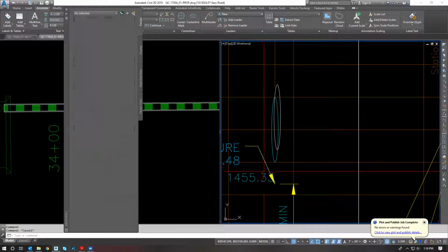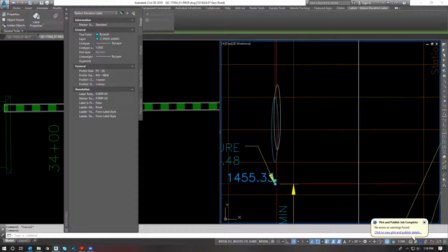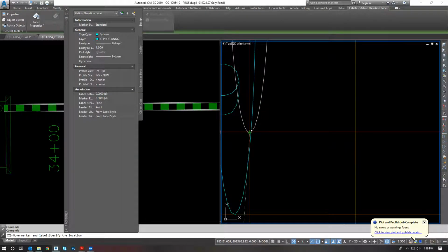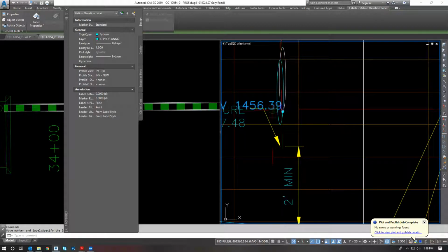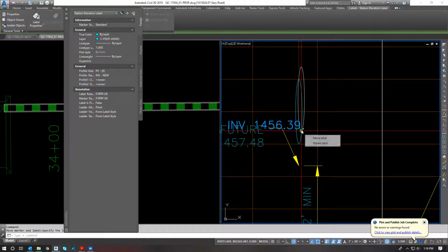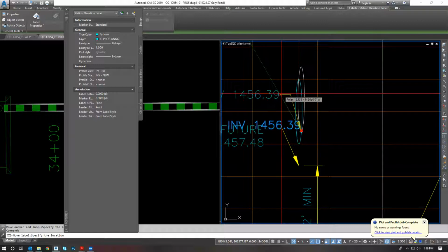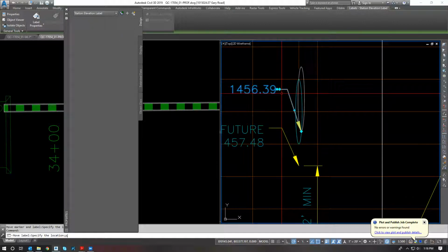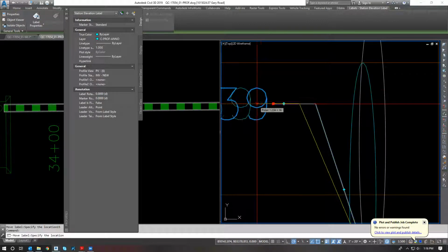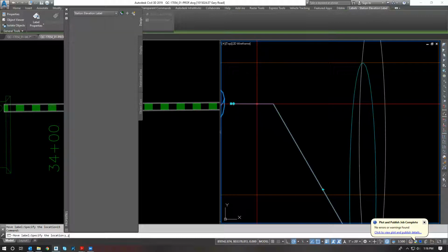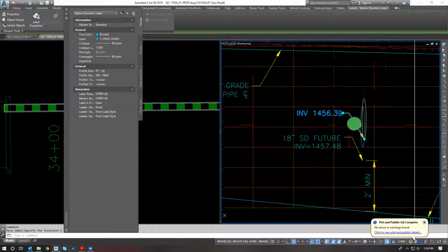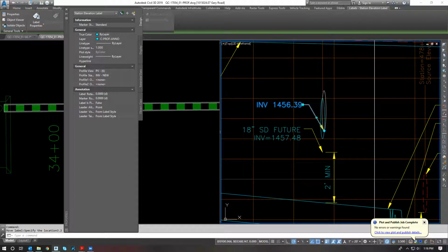So we can drag our dynamic label over to the pipe network part here, and we can be pretty confident that that is going to be accurate and that it will be much easier in the long run to update than static labels or static parts. So basic motto: use dynamic labeling. And also, if you have the ability, use dynamic networks.